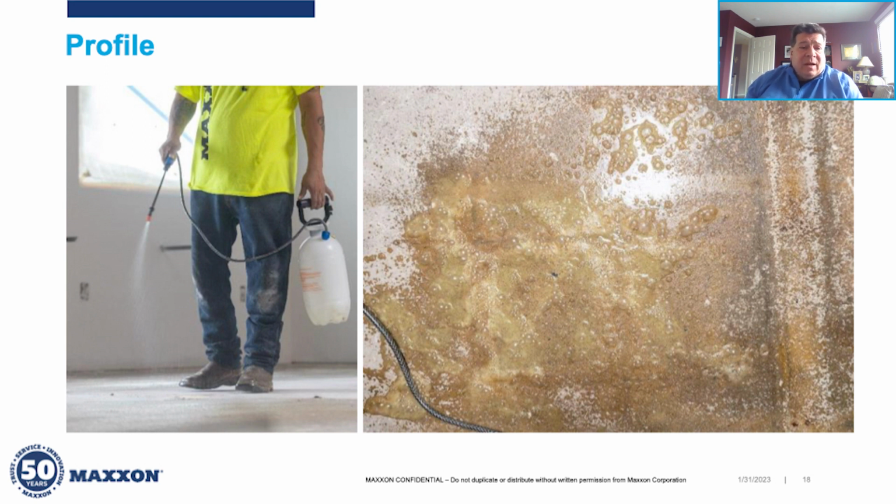Maybe you have a contaminant on the surface that you're looking to remove, and that's going to be in that 15-minute to 30-minute dwell time, if you will. And then if you're looking to achieve a greater texture or a profile in that concrete, you're looking at more in that 2 to 4 hour dwell time before the material is ready to be removed. When it is ready to be removed, you're going to spray apply or hit it with some water, which causes the solution to neutralize. So it stops the reaction and it neutralizes the solution.